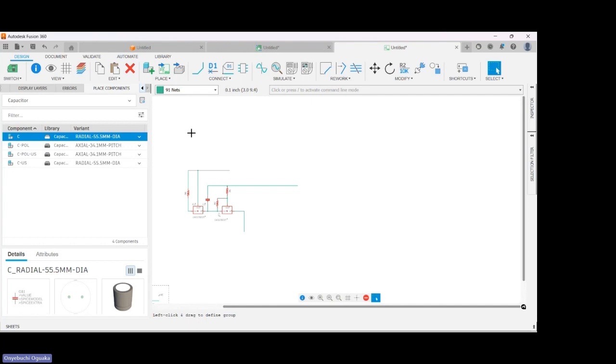With Snap EDA, it will enable you to bring in components that you do not have in your library. After switching every library on, the component that you do not have, you can import them. These are components that other people and other manufacturers have made. It doesn't take much time, and it always works in a situation whereby this one keeps you hanging.